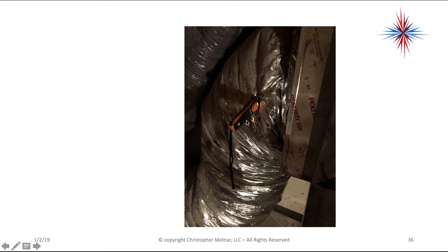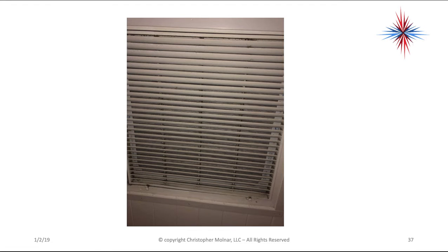Okay, this ductwork in here, just because of how it's tipped over, is severely restricted on the supply side. Can't see it very well, but the filter is also pretty clogged, and the customer here has a very nice and clean house, but this filter is severely clogged.